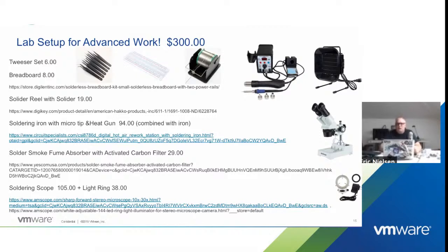At the same time, you'll want a soldering gun and a heat gun. The soldering tip is great for soldering things. If you want to solder a chip on or off, or even a resistor, take it on or off, with the little heat gun you can dial in the temperature like 350 degrees, and it has little tips there, and it aims the heat, and it'll basically melt all the pins at once. And you just take your tweezers and peel it right off. And that is super nice. It's super easy.